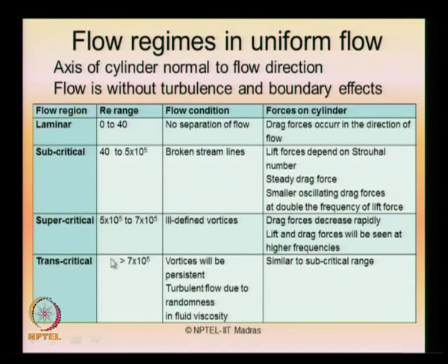Dear friends, it is very important to understand that there exists a very fine boundary or division between these kinds of regions, because once the fluid flow starts they are continuously transiting from one to the other. So you really cannot capture a subcritical or a supercritical region for conducting experiments. Of course it is very difficult to conduct experimental investigations in transcritical regions because the Reynolds number needs to be very high. So essentially experimental focus is mostly on subcritical or supercritical regions.